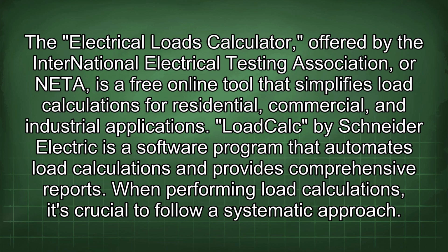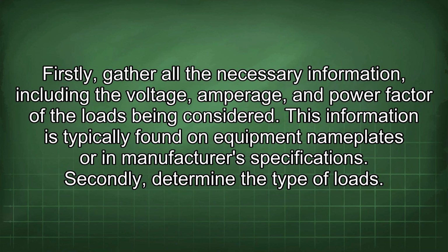When performing load calculations, it's crucial to follow a systematic approach. Firstly, gather all the necessary information, including the voltage, amperage, and power factor of the loads being considered. This information is typically found on equipment nameplates or in manufacturer's specifications.